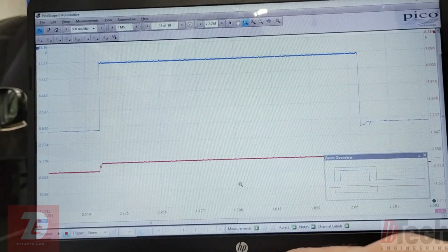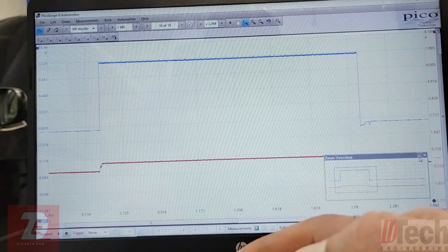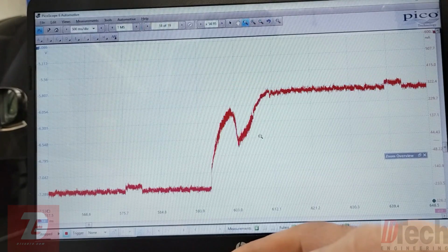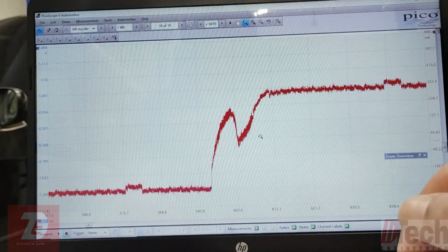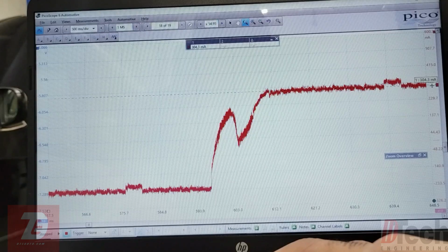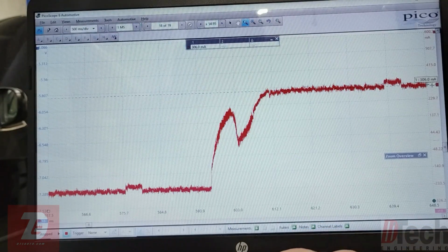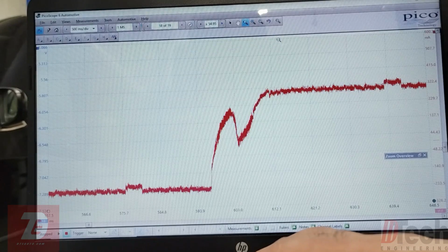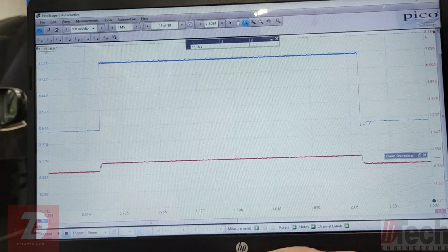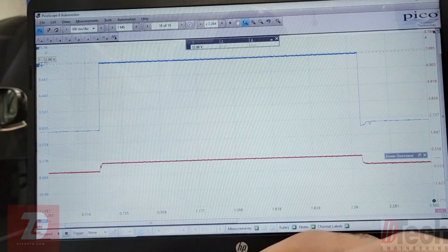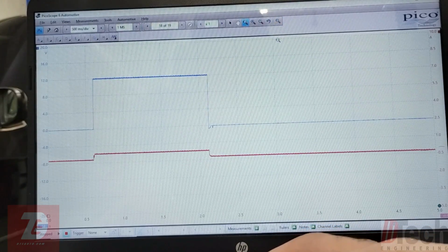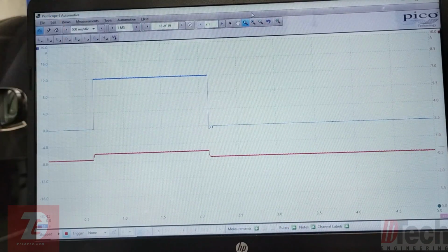Let's see. So we know it's a new solenoid. It shouldn't be shorted, and it is not. We're clearly getting the normal activation. And 300 milliamps. Nowhere near the 17 amps. And obviously we're going to get probably our full 12 volts now, not the 6.5. Yep, 12 volts.